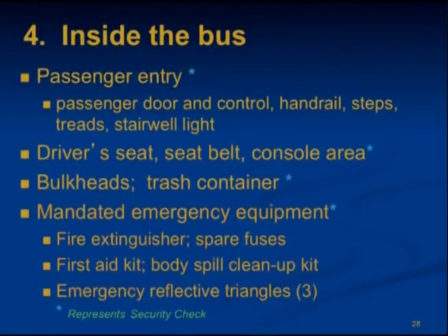The fourth topic of our systematic inspection is inside the bus. Use a flashlight when needed, and we will start with the passenger entry. Unlock the door if it's locked. Door should move freely and the door control works. No broken glass or damaged seals. Look for anything unusual before entering the bus.